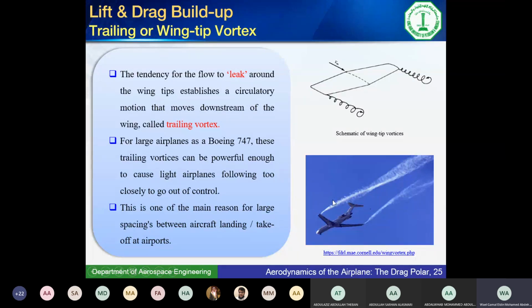If you consider a relatively small aircraft, the Boeing 727 here, you see the size of the tip vortices start to increase as you go beyond the wing tips, and they are considerable. They affect aerodynamics considerably in here. If this was a larger aircraft, a 747 for example, this would even be bigger, and that would disrupt the flow on any aircraft that's coming behind that one.